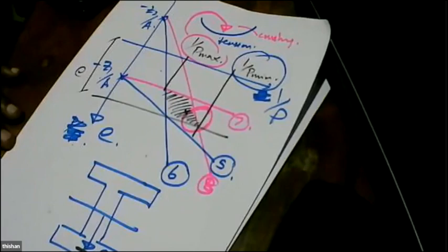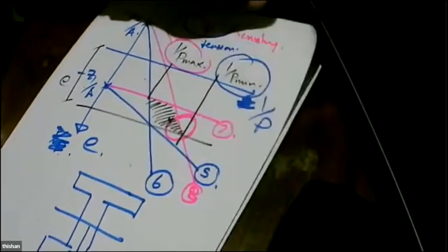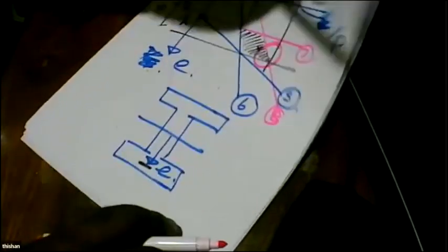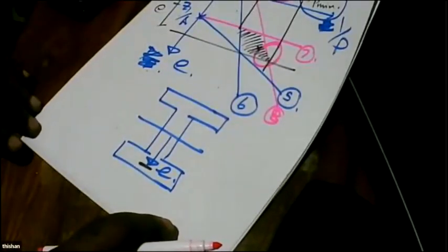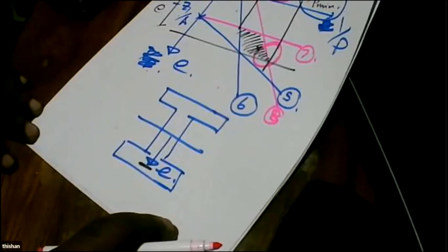So always select a pre-stress as low as possible, then you will get a very good situation because you are not going to waste any money unnecessarily. And you should know, concrete is a natural aggregate-based material, and the only factory manufactured material we use is cement, and we can use fly ash, which is a byproduct. So basically, we are getting a high strength by using admixtures and reducing the water content.